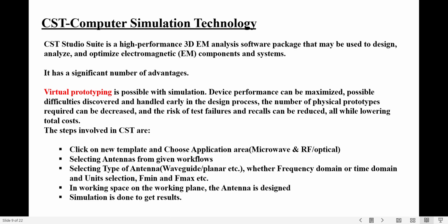So these are the steps that are done in CST. Click on new template and select antenna, select the type of antenna, the workspace, and at last simulation and getting results, all are done in CST.